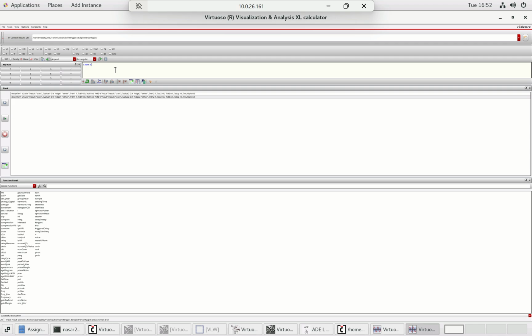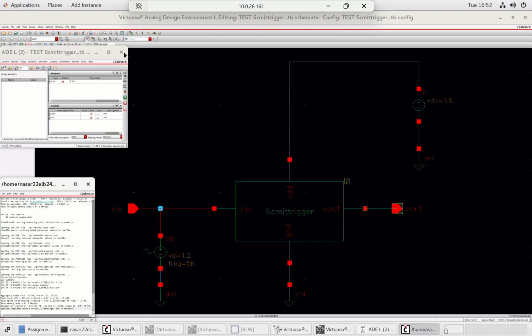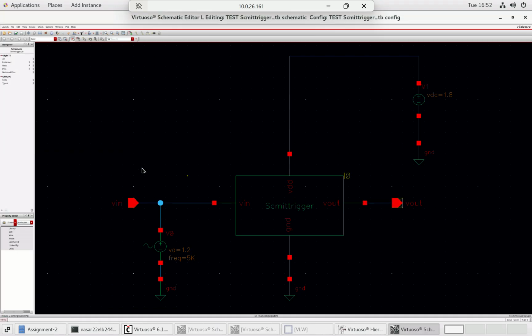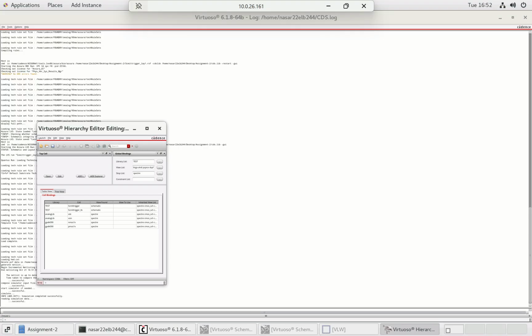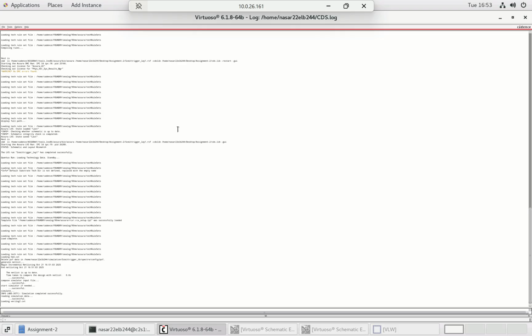The similar can be done with the post layout simulation. For example, we can cut this now, we can also cut this, we don't want to save. Okay, so that was the pre-layout simulation. Then for the post layout simulation you can go to tree, and here set instance view. If you have done the RC extraction, you can see the extracted view, and after that you will calculate the post layout simulation. Okay, now I'm not going to do that.